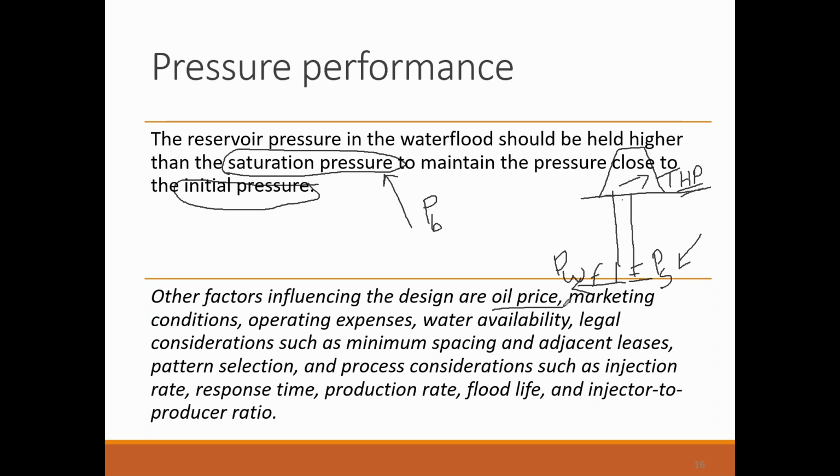So from where can you get water? In most oil fields, the produced water is treated, cleaned, and then made available for water injection. Legal considerations are also there, such as minimum spacing and adjacent leases, basically pattern selection, and process considerations such as injection rate and response time. So let me give you some more detail on injection rates.